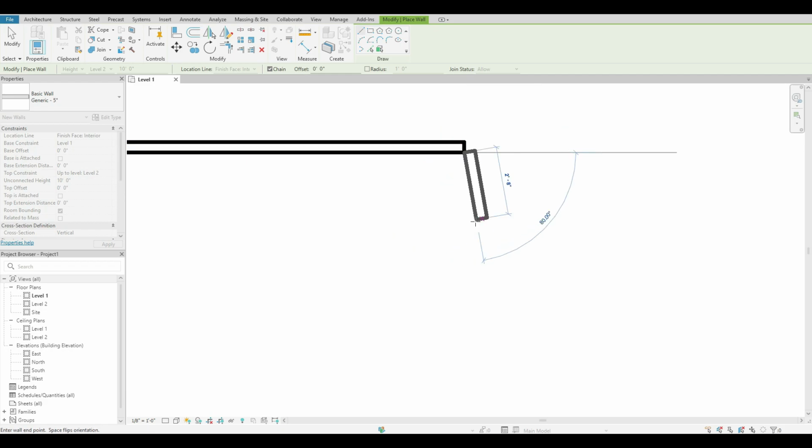So what I normally say is start off, get a feel for how you are placing your walls based on the location line, see how your dimensions are panning out, if it's meeting the dimensions you are trying to aim for, or if you need to make modifications based on what you have set your location line to. So it's going to take a little bit of practice, but that's an easy way to think about it. Just start off with how those walls are connecting.